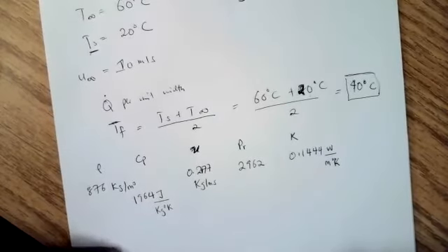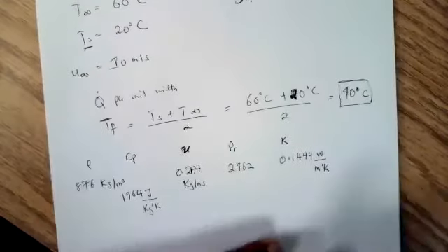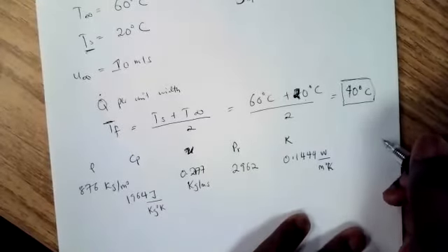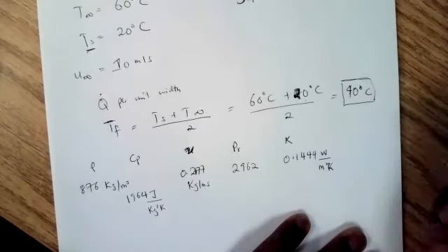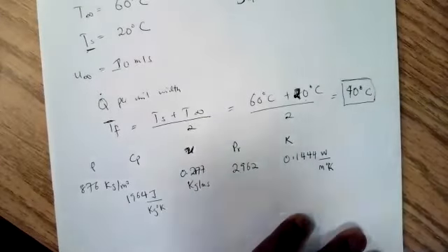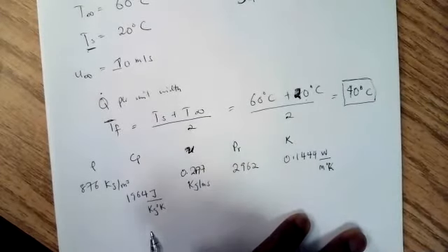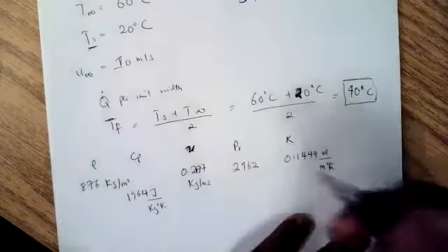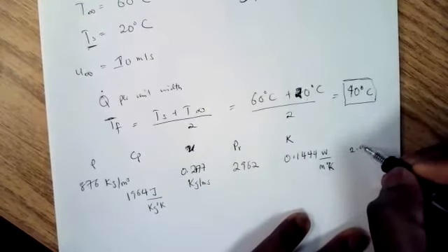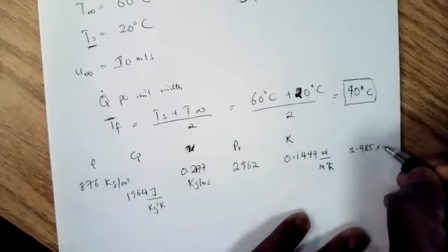Okay, is that all we have there on that table? It lists the kinematic viscosity. Okay, and what's the value? Kinematic viscosity is 2.485 times 10 to the minus fourth meters squared per second.